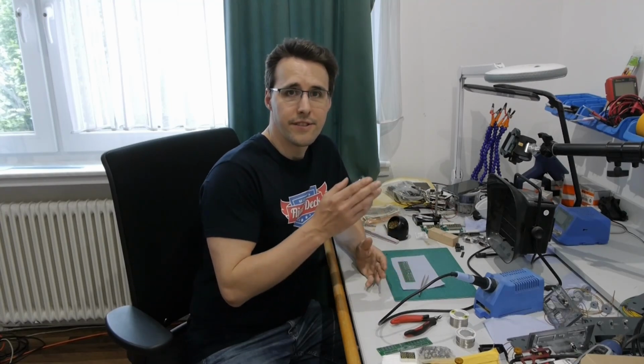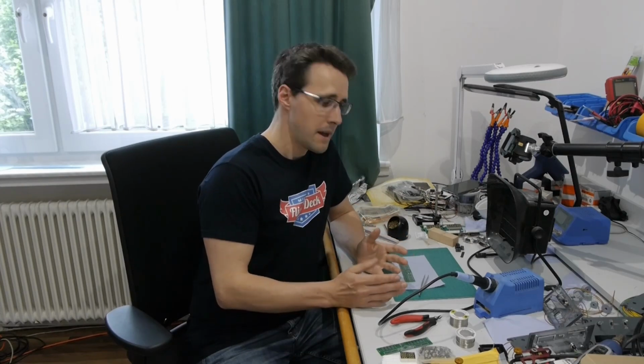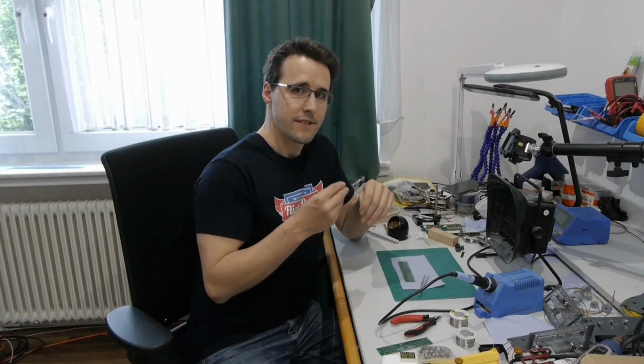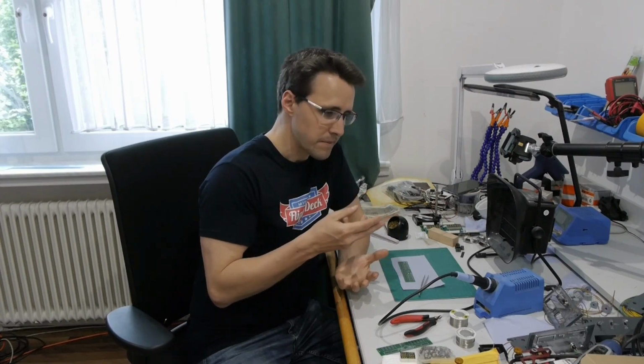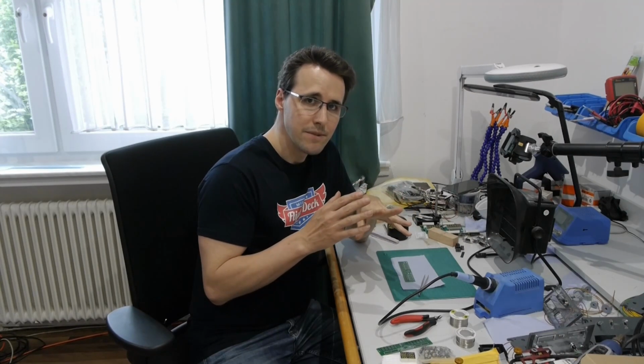The ADF panel is a little bit different than the COM or navigation panel. These panels have only 7-segment displays at the top, but the ADF panel has, beside these 7-segment displays, 2, I would call them annunciators, which give you information if the panel is in the antenna or ADF mode. So there are 2 tiny labels that become illuminated.